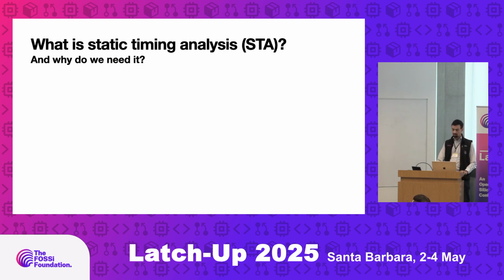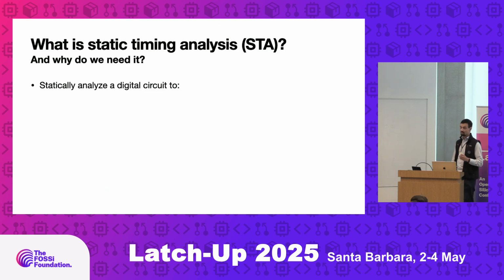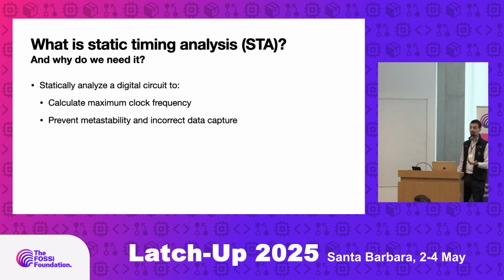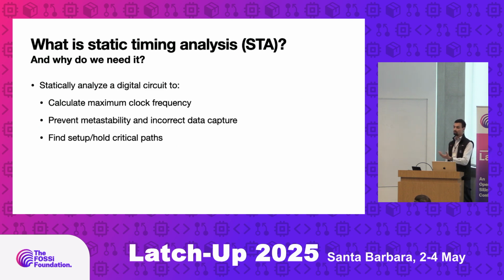OK, so what is static timing analysis, and why do we need it? The idea is that you want to statically analyze a digital circuit to calculate the maximum clock frequency I can run this circuit at. You want to prevent problems such as metastability and capturing the wrong signals at your flops. You want to find the critical paths inside of the design, so which paths you should worry about the most.